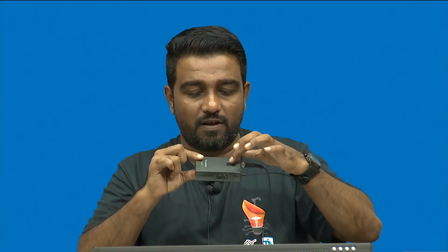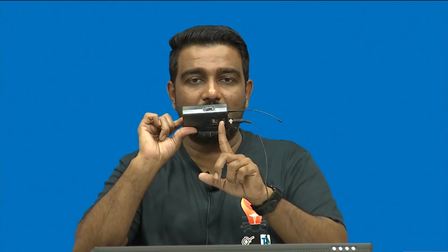But if I want to create a diaphragm, let me give you an example. If this is the wafer and this is the sensing area, I want to create a diaphragm exactly on the back side of this sensing area. That means I should align it on this side. How would I know it is perfectly aligned with the front side? That is what is called front to back alignment, and to create a diaphragm exactly below this particular sensing area, this is where your front to back alignment will work.